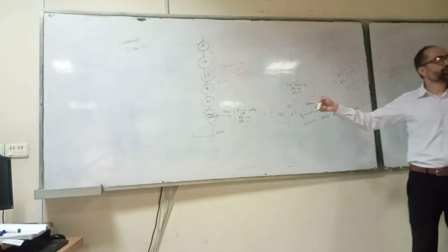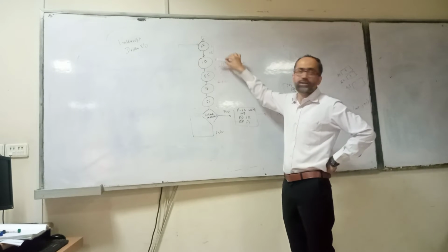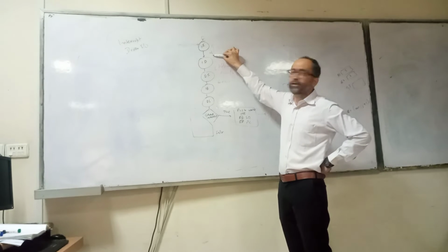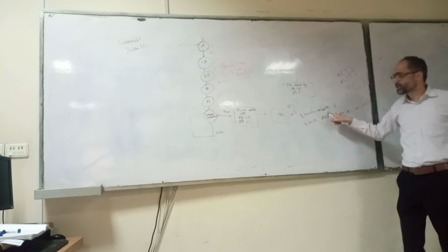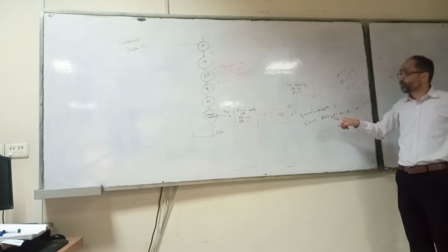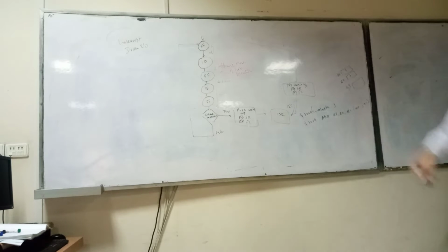These are different phases of instruction execution of any instruction J. Let's assume the interrupt arises here. First we will complete instruction J. When it's completed, control will be transferred to the interrupt subroutine. Let's assume this is an ISR, interrupt subroutine, and its address is $4000. So control will be transferred to this interrupt subroutine.